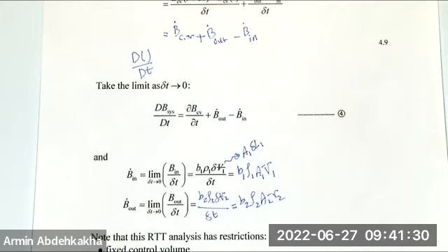But being in a fixed position in the domain and just checking the boundaries and the velocity, because you only need pressure sensors over the boundaries, then studying the fluid in this method, control volume based or the Eulerian method, is much easier. It's less energy, less time, and it's possible. Most of the time, it's not possible in the Lagrangian approach.